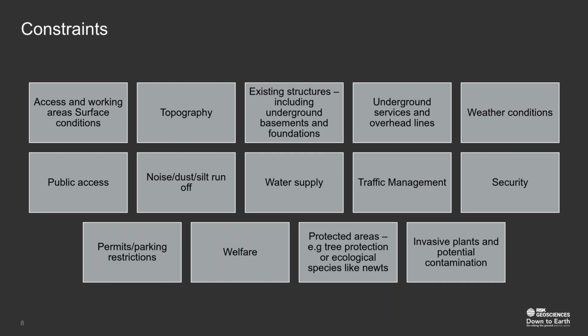If you haven't already visited the site as part of a previous phase of work, it's really important to include a site walkover in your planning phase. It's also important to request data from the client. For example, do they have any service plans? Is there any as-built drawings? Is there any previous reports that you can have a look at?